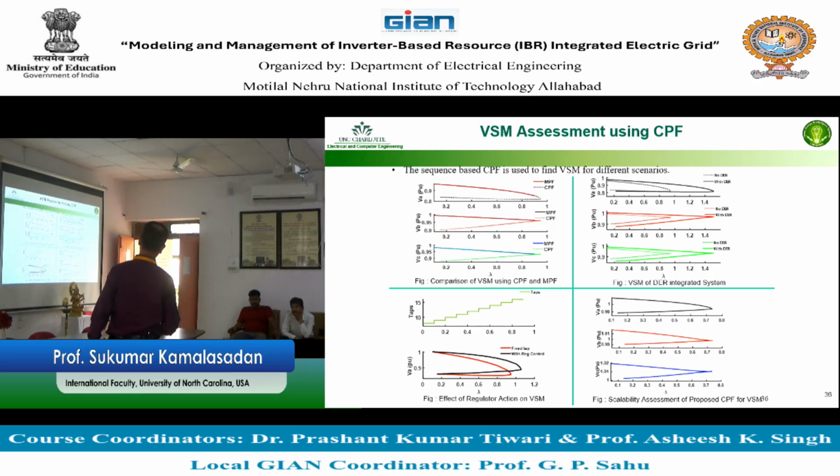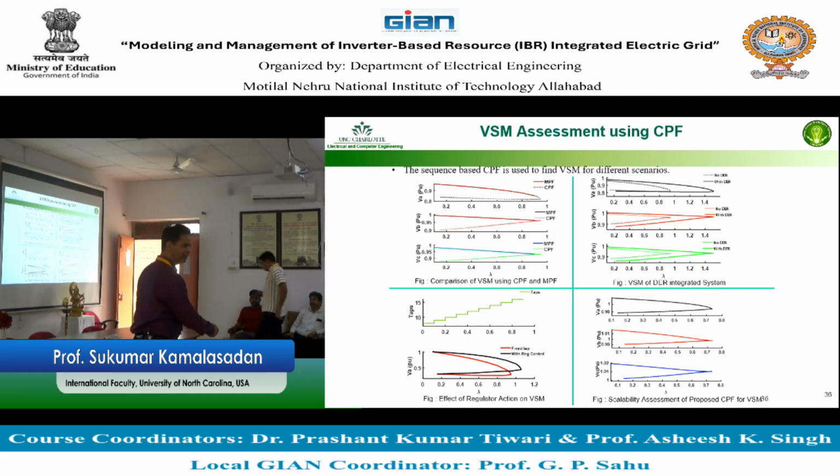You see these PV curves plotted. This is the PV curve without DER and with the DER. What happens when the DER comes in place? If DER is pushing the power, the PV curve is kind of extending because DER is getting more power onto that, because it's going to the light load condition. So you can see that.